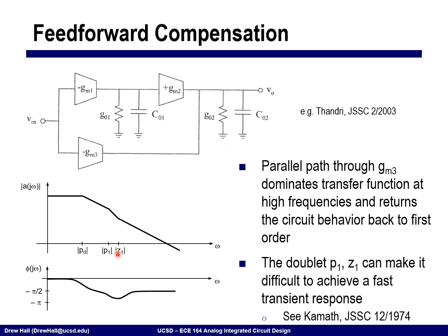This will introduce a zero in the circuit from this alternative path to the output, and we're essentially using this in order to stabilize the circuit. This can make it rather difficult to get good frequency response out of the circuit, but is often needed if you need lots of gain, and especially in newer technology nodes where gain is very hard to come by.